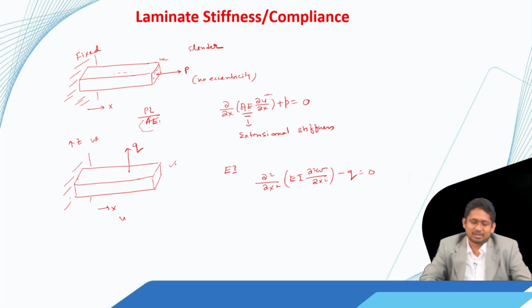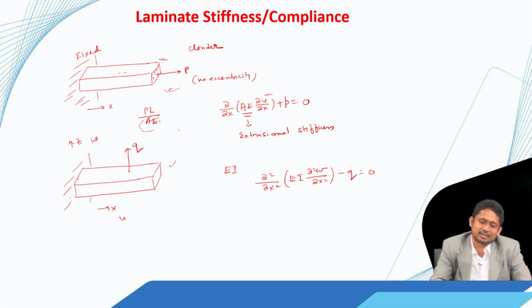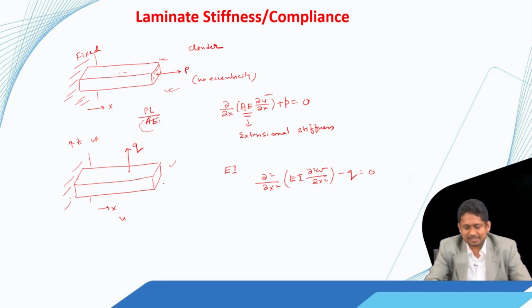and that helps us get rid of some of the dimensions in the problem. Now, this bar problem can be extended to 2 dimensions. Then we have normal force along x, normal force along y, and shear force in the xy plane, and that becomes a 2 dimensional problem. So, the properties would be integrated along the thickness only. Similarly, this beam problem can be extended to 2 dimensions, and that becomes a plate problem. So, there can be bending in both directions as well as twisting can also be there, and here also we integrate the properties along the z direction only.